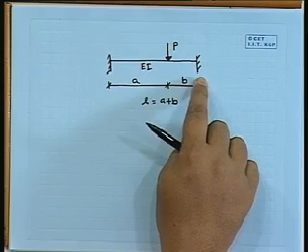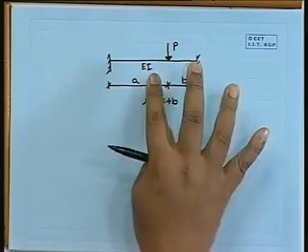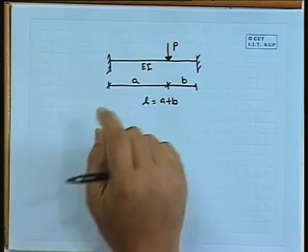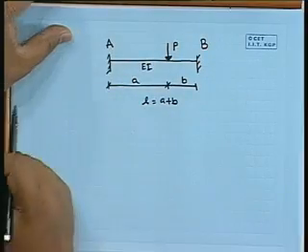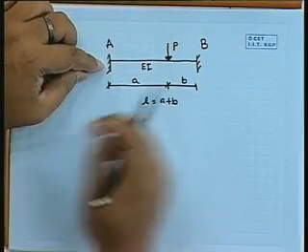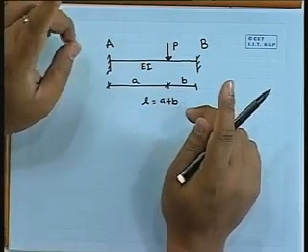There is another possibility. We can make both the clamped supports into hinge supports, take some reactive force and allow the rotation. So it will be a simply supported problem with moment. If we say this is A and this is B, there will be a moment MA and a moment MB. That is one option. Another option is we straight away remove that support and take a vertical reaction and a moment, right. So in two ways we can handle the problem.